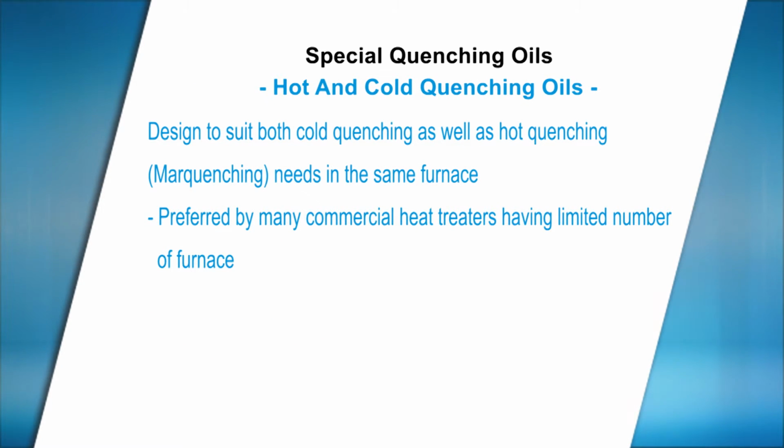As the name suggests, hot and cold quenching oils are specially designed to provide quenching properties of cold quenching oil and also of hot quenching. Customers such as commercial heat treaters prefer a single quenching oil to suit the varying requirements in the same furnace. They have a limited number of furnaces, but at the same time have to quench a wide variety of components and steel grades.